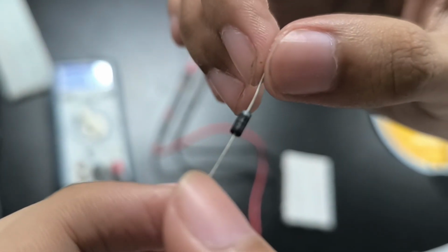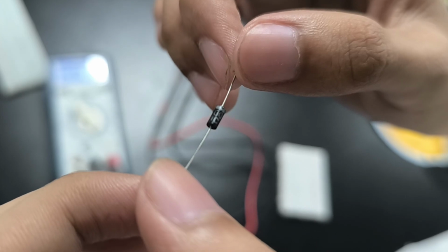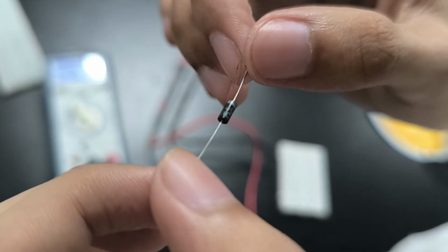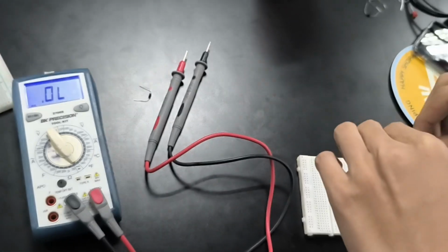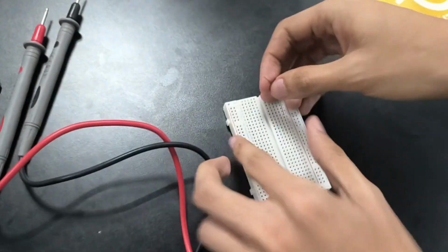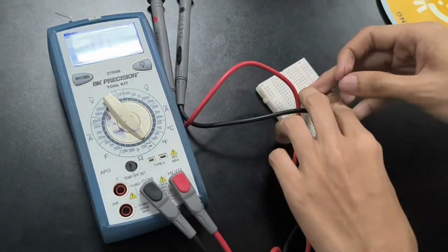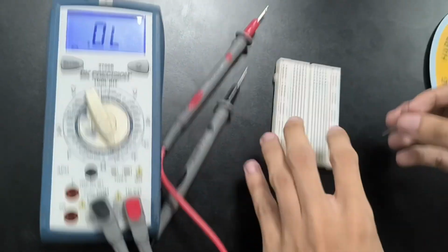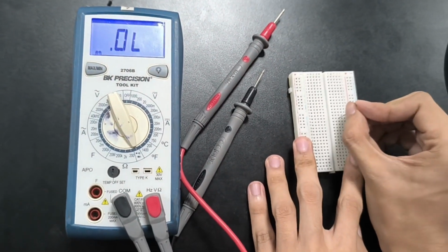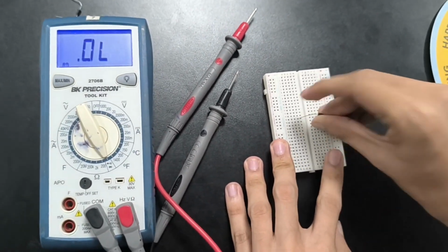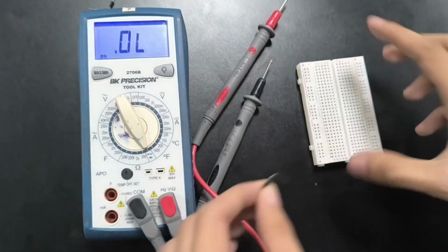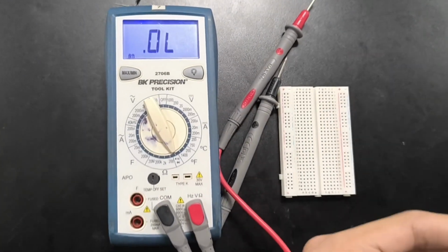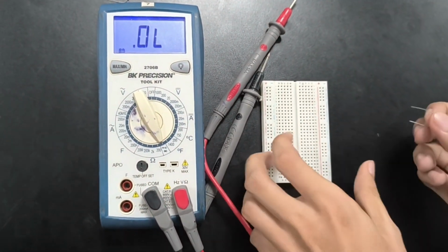Start by identifying the diode and checking whether it's working properly. Using a digital multimeter, I'll first determine which end of a diode is the anode and which is the cathode. By setting the DMM to diode test mode and placing the red probe on one end and the black on the other, a good diode will show a forward voltage drop, typically between 0.6 and 0.7 volts for a silicon